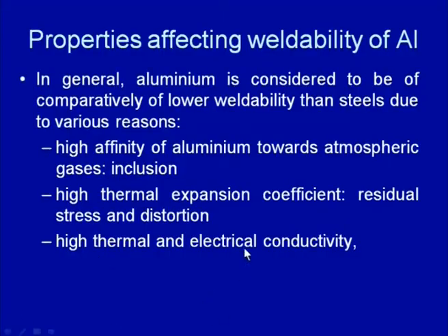Similarly, electrical conductivity plays a big role in spot welding of aluminum alloys. Because of the high electrical conductivity, it decreases the electrical resistance heating, and the heat which is developed at the interface. So, because of this it requires a higher current setting for developing spot welds in aluminum alloys as compared to steel.